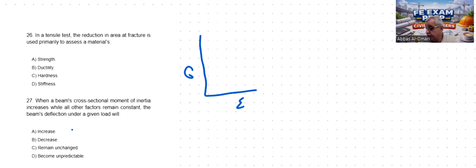It starts linear, it goes up a little. So this is strain hardening. So this point is U, ultimate strength. So this point is the fracture. So in this part, this is the necking, when necking occurs just before fracture. So this is a measure of the ductility,